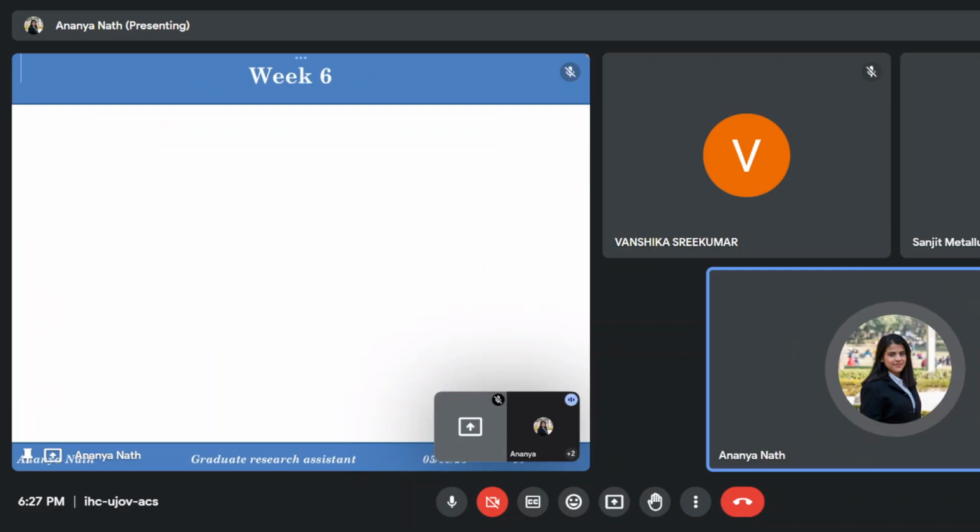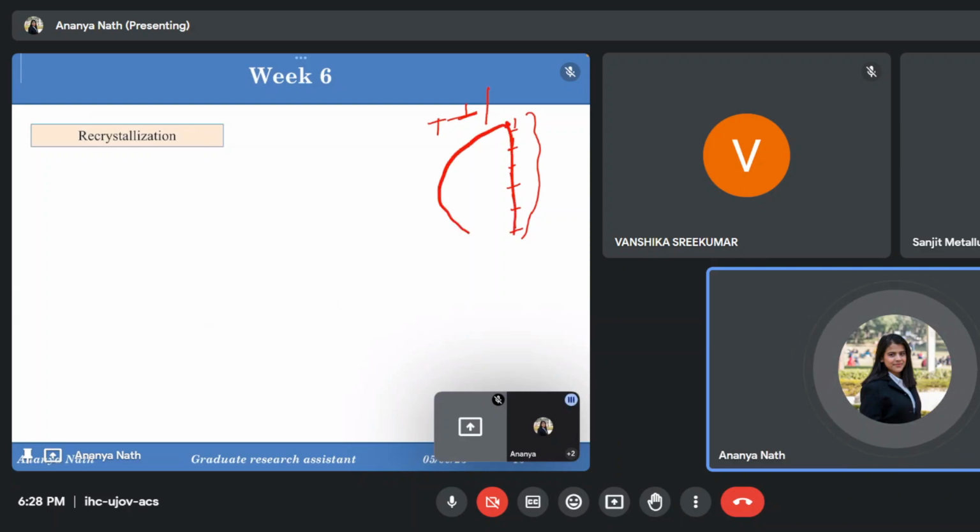So the next topic was polygonization. Polygonization means if there are some dislocations, if this is the grain boundary, and there are opposite sign dislocations, they will meet and make a continuous line. There will be no dislocations anymore. But if they are of the same sign, they will try to get arranged in a low energy configuration. This is what they call low angle boundaries. If they are aligned like this and like this, they can make a separate grain, which will be taught in the upcoming lectures.